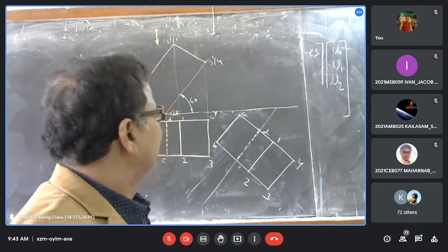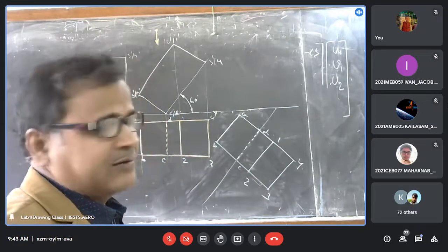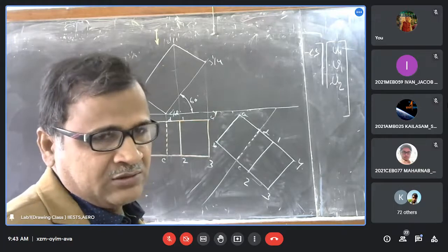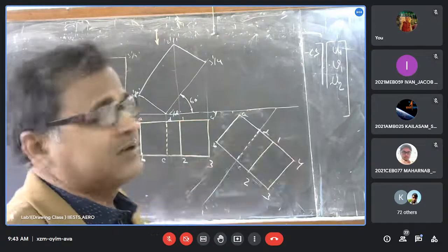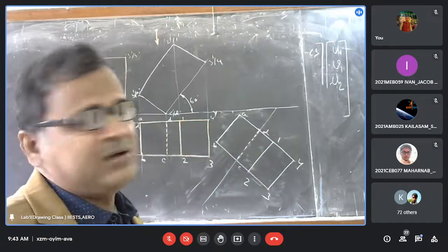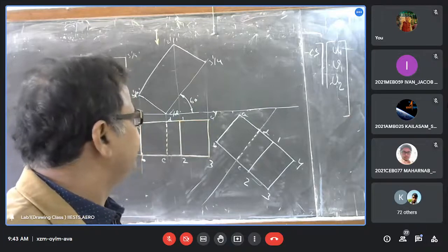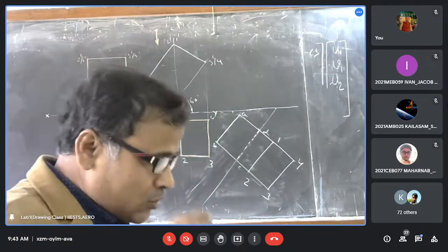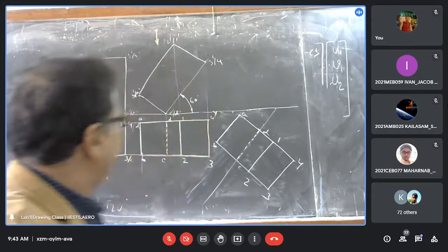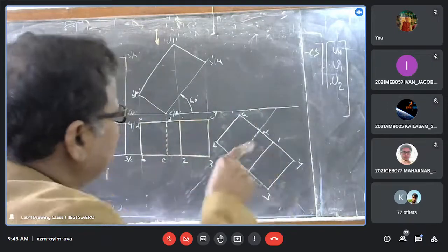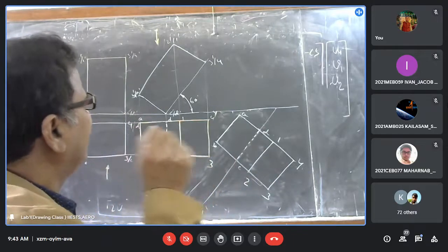Now you have to draw the projection from the plan point and also draw the projection from the elevation side, and you find the intersecting point and then you find the complete elevation. Now can you tell me why we are rotating in the clockwise direction? Can you tell me which corner point we cannot see?